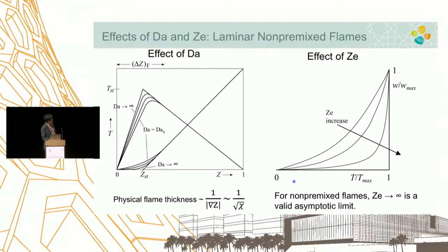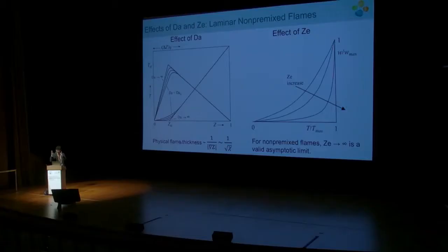Just to show you a graphical image of that, I have to give an example of 2 different scenarios. One is a non-premixed flame, and the other is a premixed flame. I will revisit this definition of the mixture fraction, but this is a non-dimensional coordinate that goes from the fuel to the oxidizer stream. The flame is established in between, at the stoichiometric location, and temperature reaches the typical adiabatic flame temperature. As the Damkohler number, being the chemical reactivity, goes very large, the reaction becomes intense.